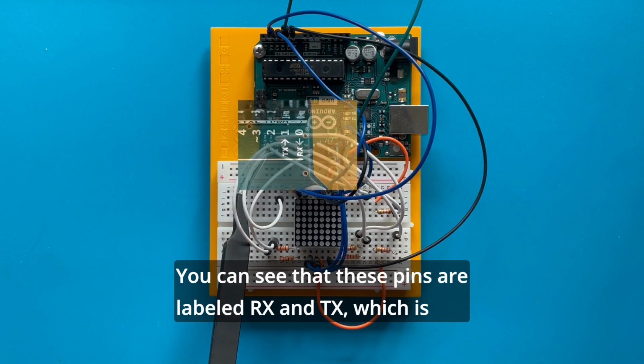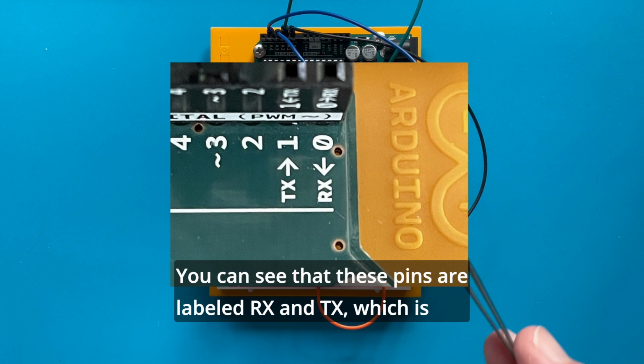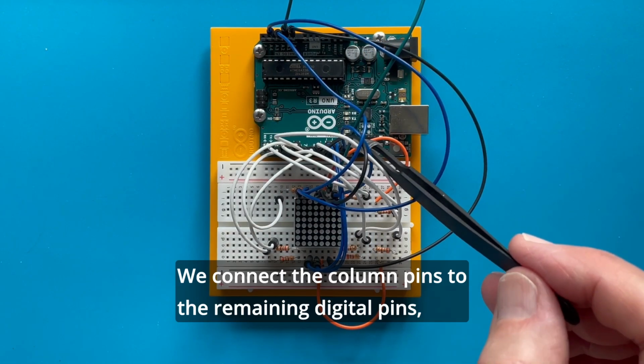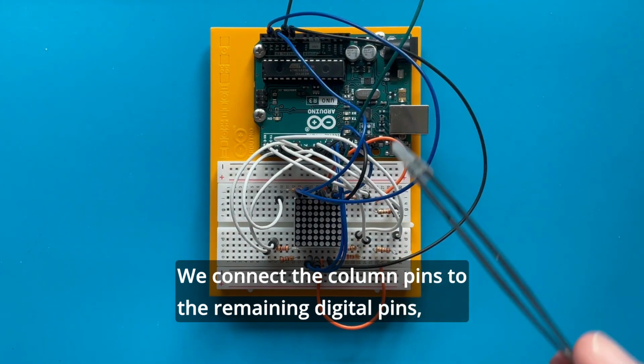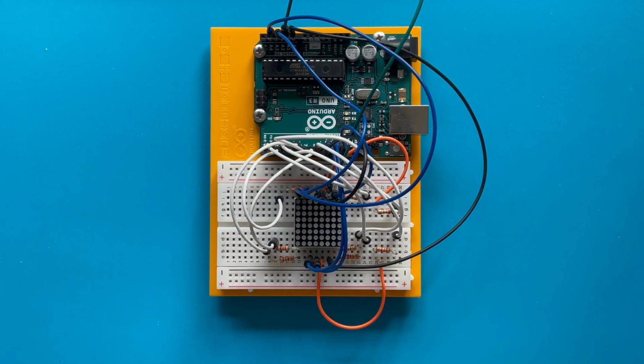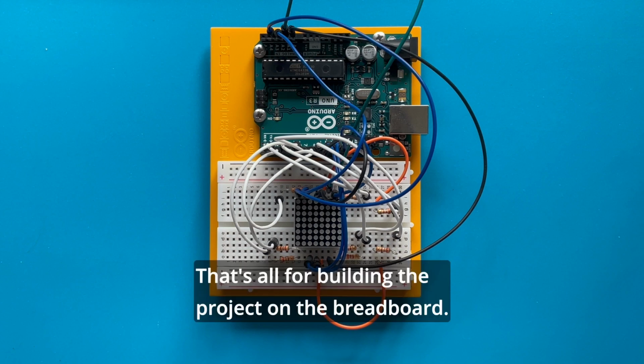You can see that these pins are labeled RX and TX, which is short for receiving and transmitting. We connect the column pins to the remaining digital pins and continue with the analog pins A0, A1, A2 and A3. These can also be named 14, 15, 16 and 17. That's all for building the project on the breadboard.